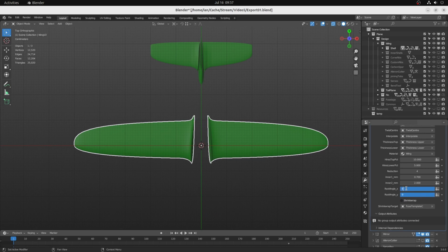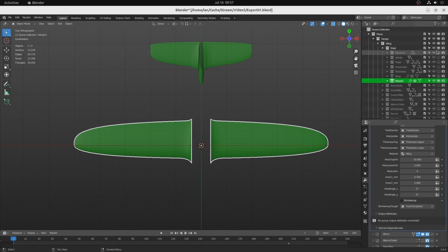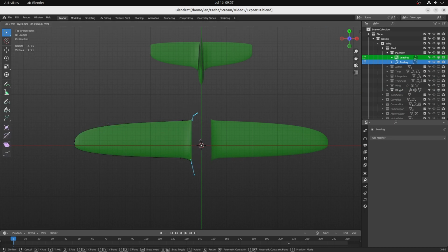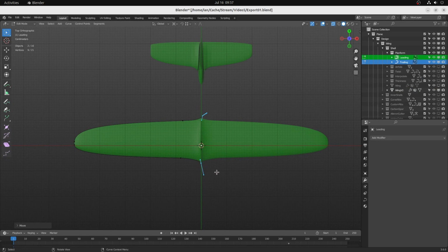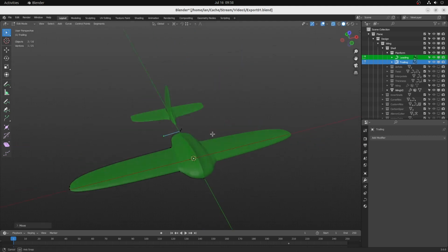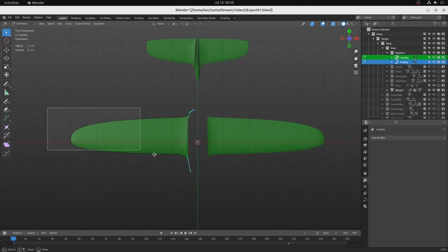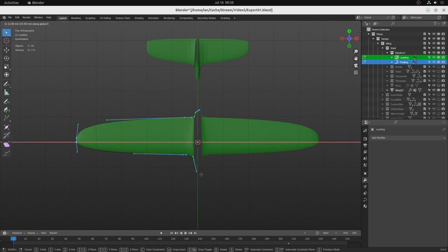But the gap between the wing halves is no good either. I've thought of trying to approximate a fuselage with the wing planform settings and then setting the twist of that section to make that area non-lifting. But actually, I think that would probably place too much incorrect emphasis on the impact that the fuselage would have on the lift of the wing. We could just extend the root area, but I'm thinking it's best just to move the two pieces of wing together to keep the total wing area the same.